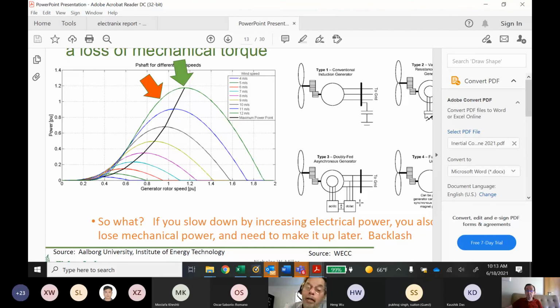And it's not completely unlimited for a Type 4 too, because you still got volts per hertz and other issues at very low frequency, even for a full converter. It's less driven by the converter and more driven by the insulation and the flux management in the full converter. So full converters probably can't go much lower than that either, although the physical limitations are a little different. Yes. Thank you very much, Nick. Yep. Thank you. I'm going to give the last question here to Chao Wu.